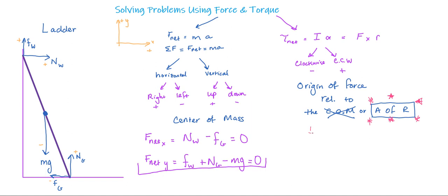It depends on, first, what you're solving for. What are you looking for? Okay, that's the first thing to consider. And once you've considered that, then you decide to choose an axis of rotation that eliminates the most terms possible. Now that would just be because you don't want the problem to take 6 years to solve or have lots more possibilities for errors.